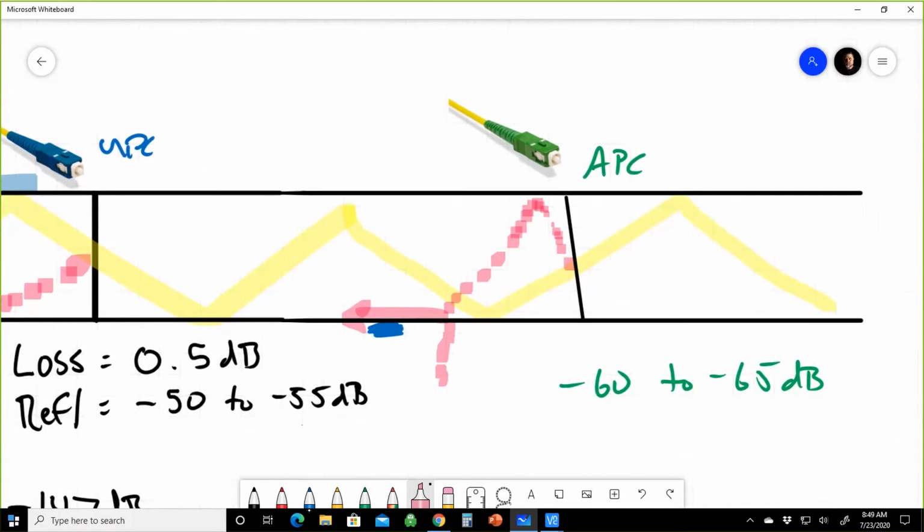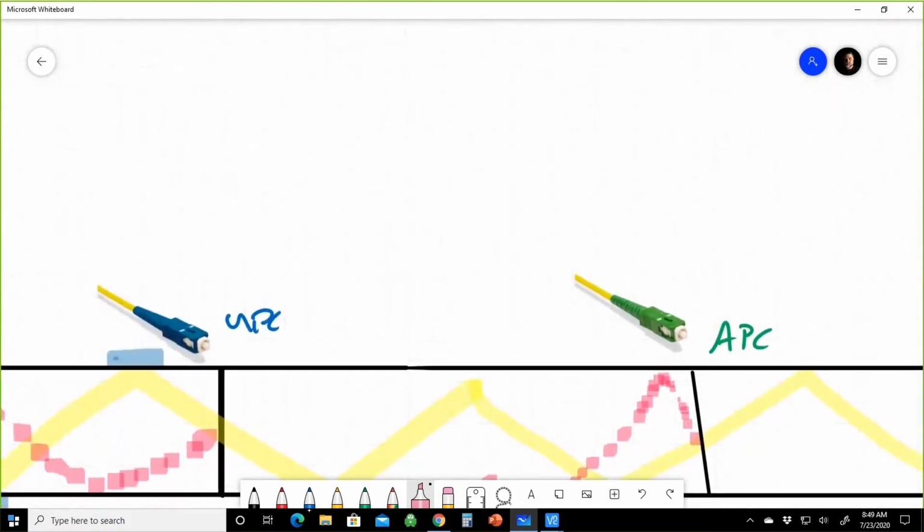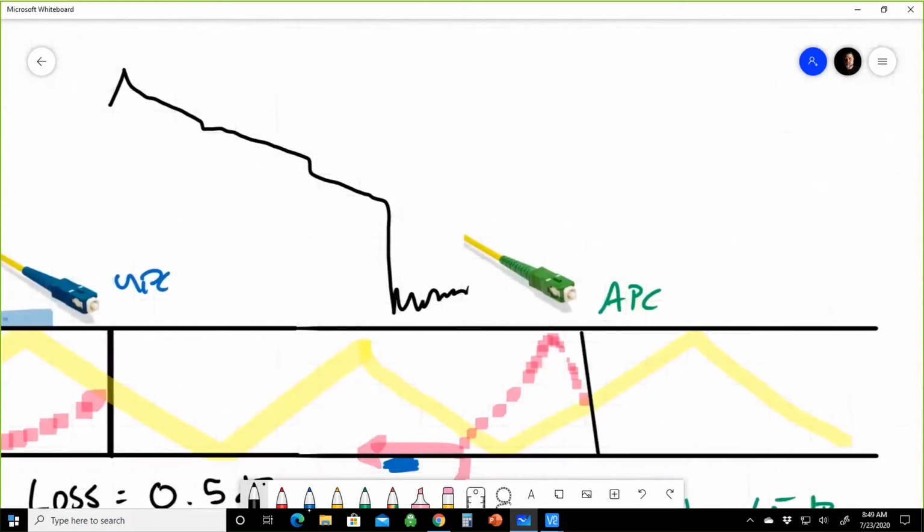This is why when a fiber is broken, it kind of rounds off, right? We've all seen it on an OTDR trace, and I'll draw it when we have the OTDR trace. But when you look at an OTDR trace and you have the launch and whatnot, if it rounds off like this, when I was in field ops doing troubleshooting, if I saw something round off, that usually meant that I had an open. Or it was plugged into something absorbing light. Basically, I wasn't getting a nice cleaved finish from an open.